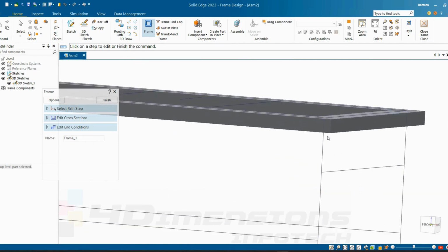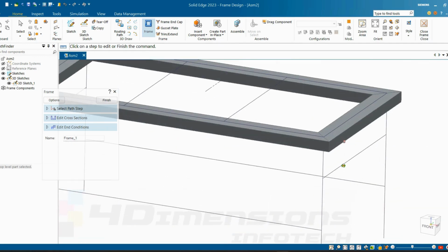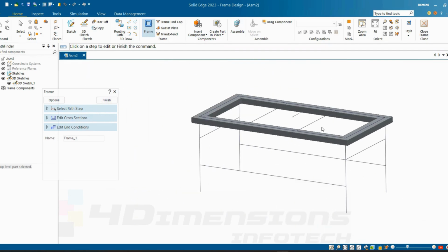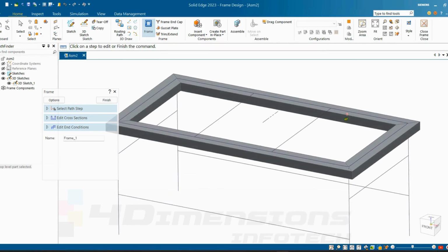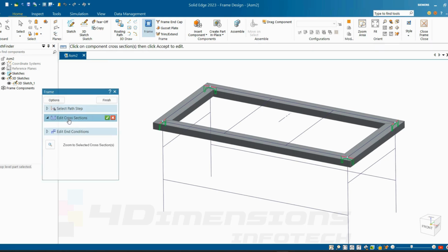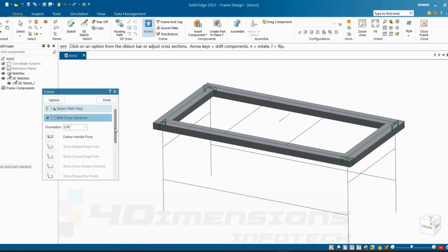It is oriented at the downward side with the opening side. That's why we cannot see it properly. So we'll take this orientation with 90 degrees angle. For that we need to go for the second option. We are going to say edit cross sections. So in edit cross section you just need to select the option, say OK, and here you will get three